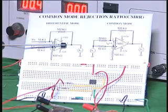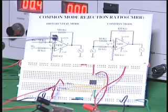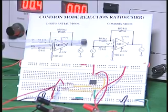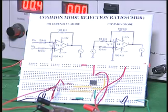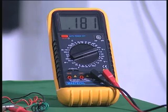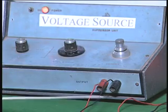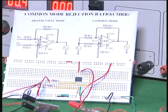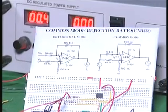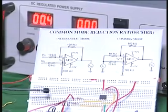So, I am going to do these two and measure the output in each case. The difference in voltage in this case will give the AD. Then I measure the output and the corresponding input here, that will give me AC, and I will divide one by the other to obtain the CMRR, right. I have used one voltage source, VI1, 0.5, which is actually 500 millivolts, corresponding to 0.5 volts, connected to one of the input terminals. I have also used a variable power supply which is not being used here, and its output voltage is around 0.5, actually 0.48 or so, and that is what is given here.